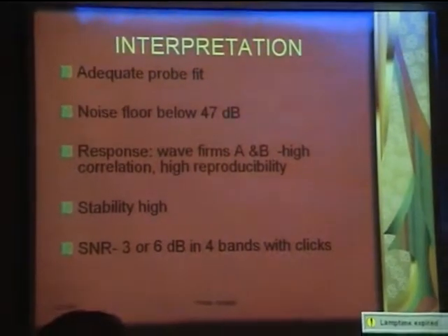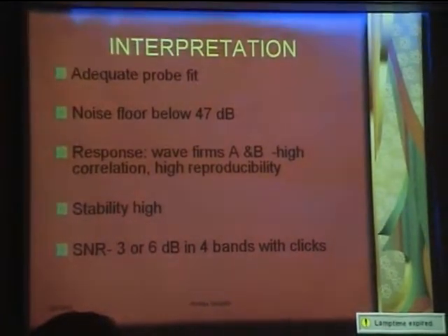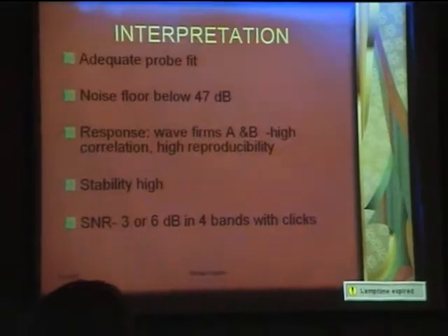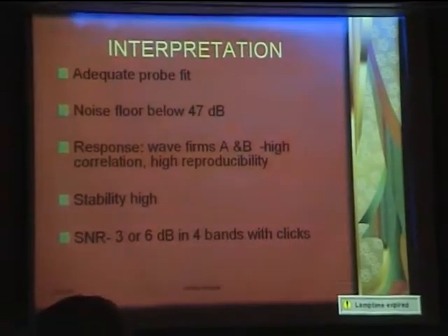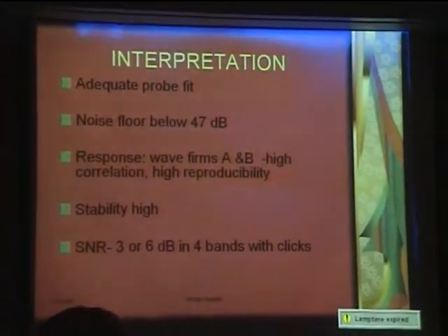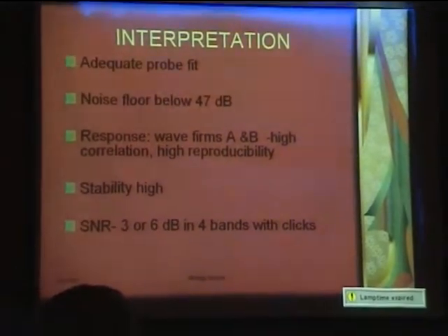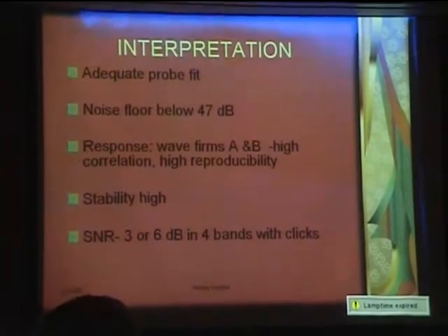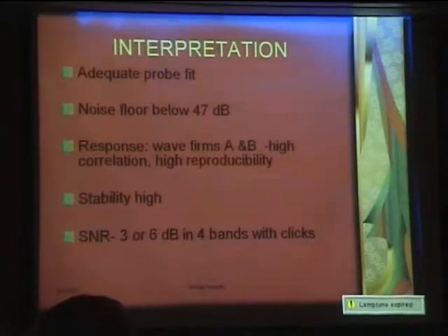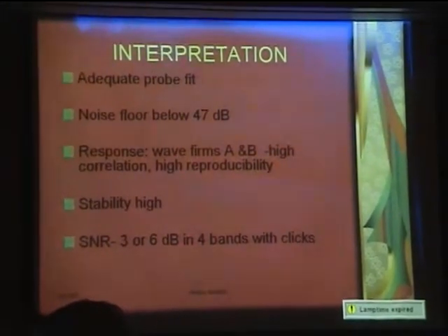We need to have an adequate probe fit, and the noise floor should be low, which is a major problem in most of our testings. We need to have a very silent environment, even if not sound treated, we need to have a silent room. The noise floor should be less than 47 dB in order to get a good signal to noise ratio.